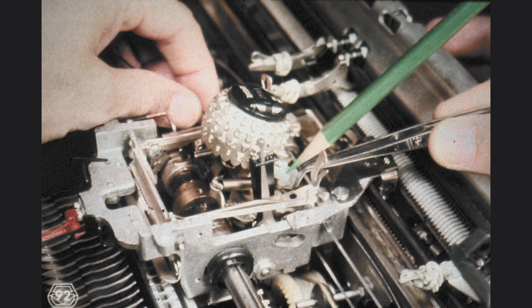It is important to avoid bending the tape too much, which can happen easily when trying to remove it from the tilt pulley sector. On older machines, instead of the nylon pulley indicated by the green pencil, we might find a metal pulley or even a horizontally mounted metal pulley sector on the geared tilt mechanism. Whatever the modification, the basic process of removing the tilt tape is the same as the one we have demonstrated.